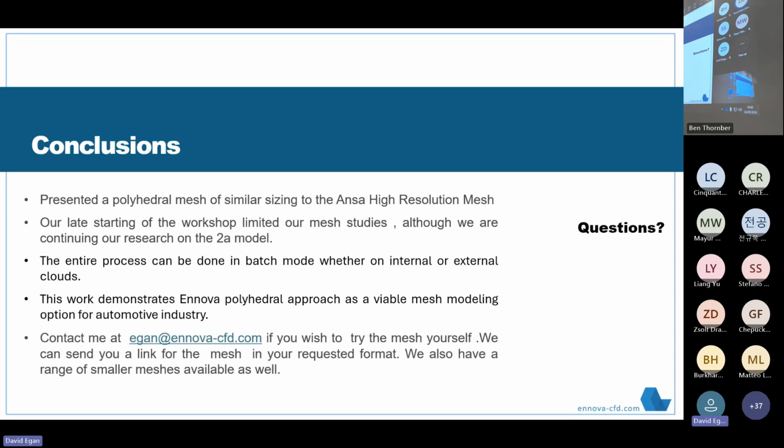And that's why we're very keen on learning as much as we can on the automotive side, to repeat what we've done in aero. For example, on a trailing edge of a wing on a plane, typically 16 to 17 grid points are required to capture the flow for a transonic flow. Stuff like that has been found out just empirically over time.